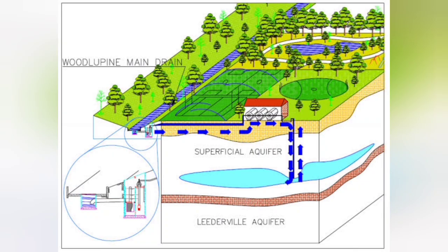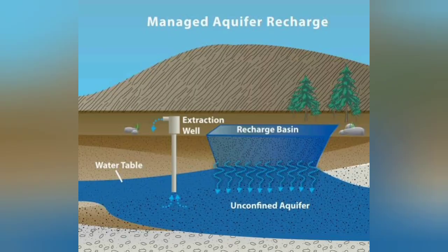Now we discuss the aquifer geometry also. The data on the subsurface hydrological units, their thickness and depth of occurrence, and to bring out the disposition and hydraulic properties of unconfined, semi-confined and confined aquifers in the area. The main stress is on knowing whether the subsurface rock types are sufficiently permeable or not to maintain a high rate of infiltration during the artificial recharge.